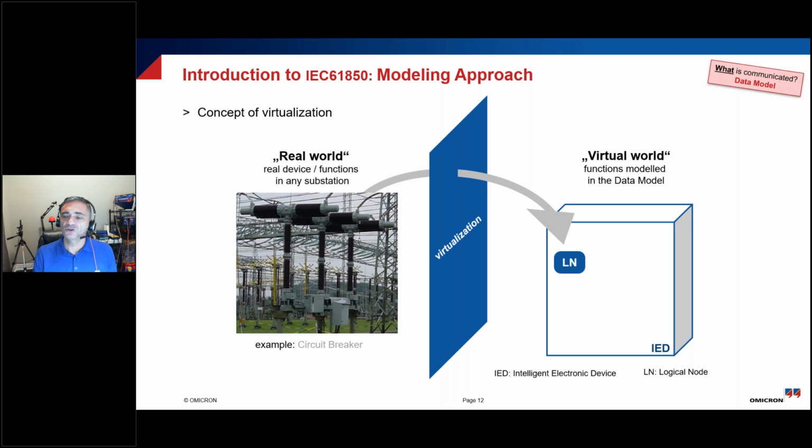That logical node describes this device, this circuit breaker. It'll have a unique name for that type of device called XCBR. In the IEC 61850 protocol, XCBR means a circuit breaker, that big switch. There could be multiple switch models inside this IED. It could be controlling multiple breakers, and so they have multiple instances of it.